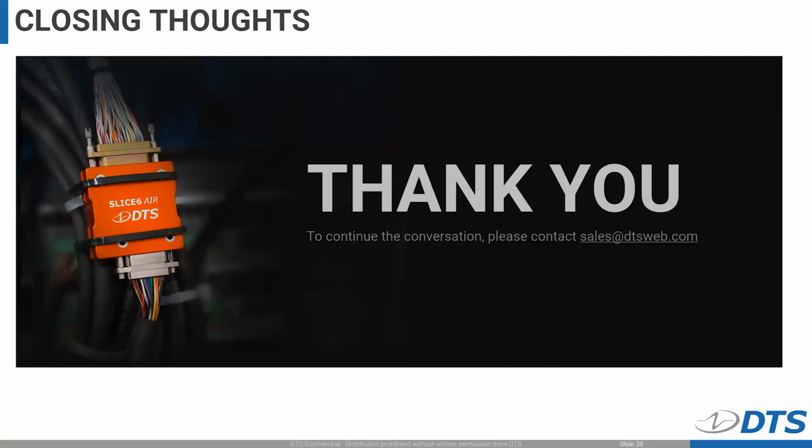Hey, Jim, Mike here. Hi, everybody. Thank you for being here for this webinar today. I just want to throw out, there was obviously a lot of interest in filtering. And one of the things that we've done with the design of this product is we've put in a very, very flexible and programmable analog filter. And what maybe is not immediately apparent is we can support fundamental sampling rates up to roughly 500,000 samples per second. And the analog bandwidth is something that we can adjust very easily with software.